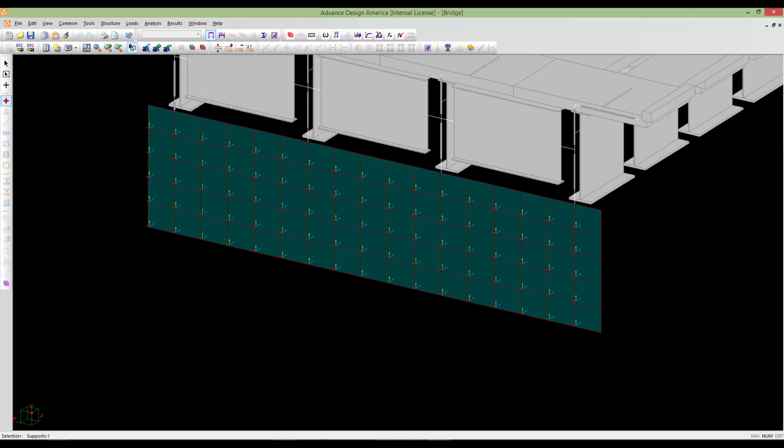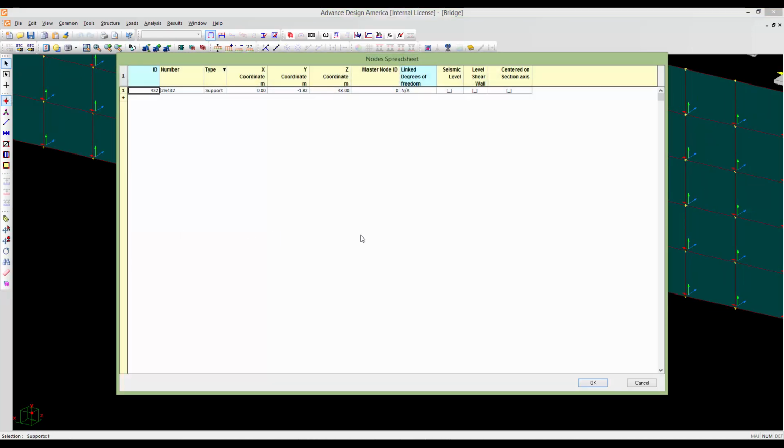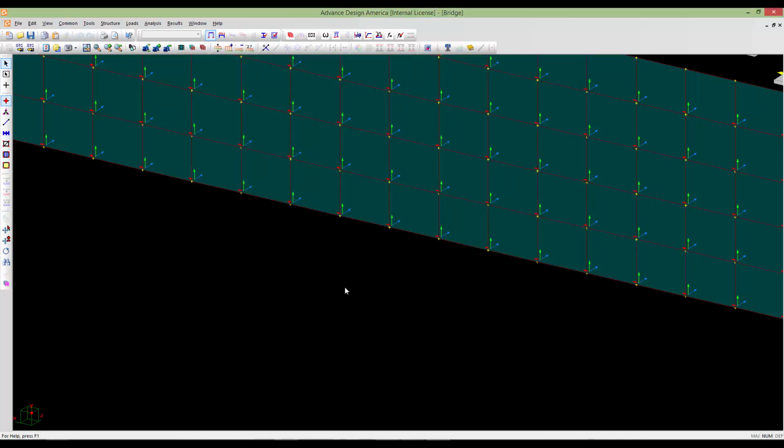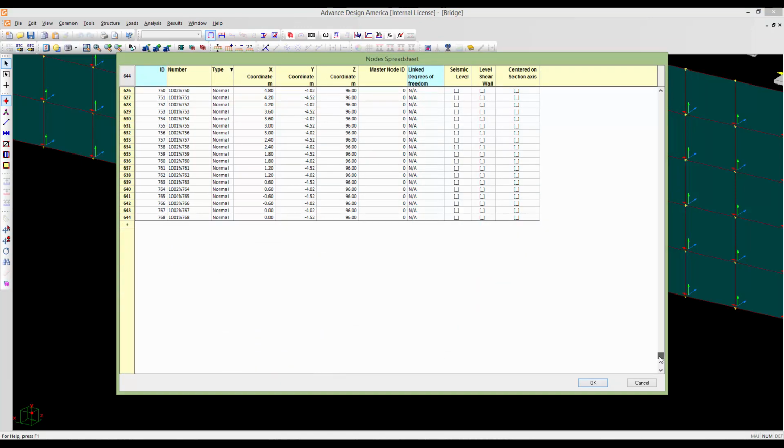here. Okay, you have all of the nodes here. Go to the final one here. Add a new node. Let's name it 2000. It will be a support, and the coordinates will be x 4.5 and y -5.